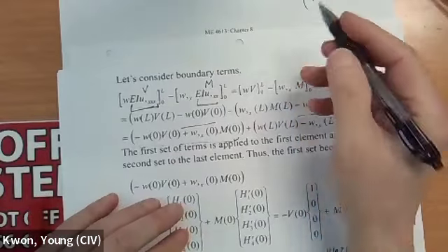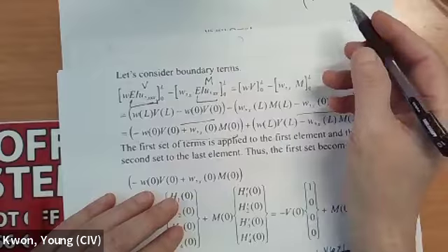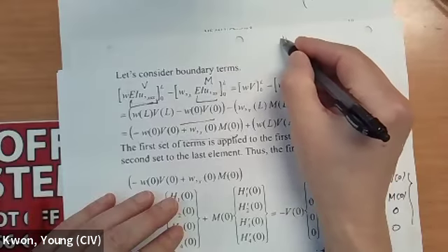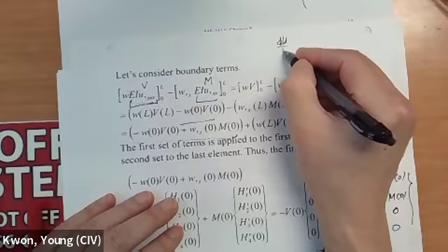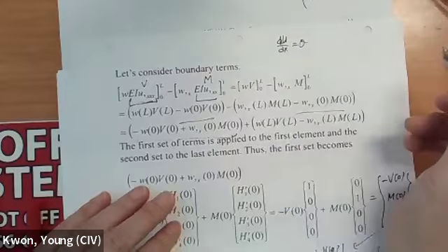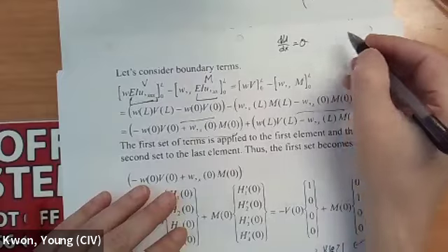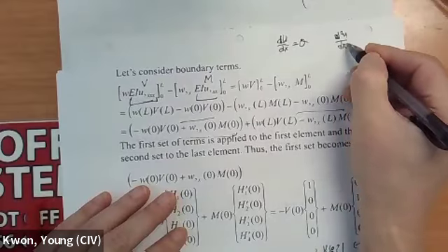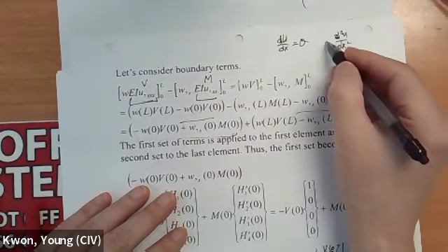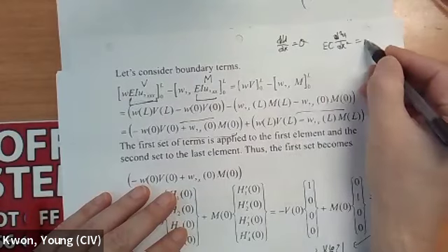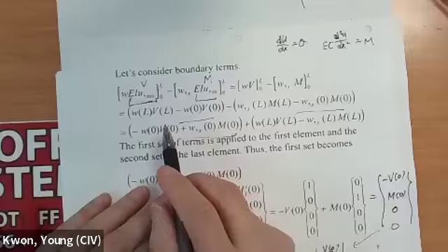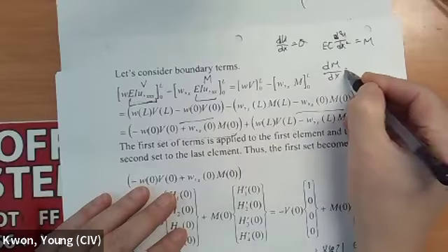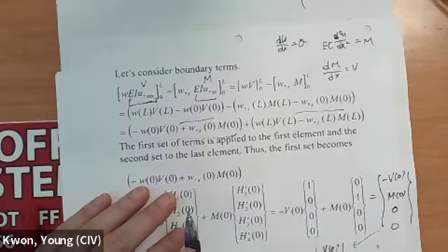In the derivation of that beam bending, you take a derivative of that, which is slope, right? And if you take a second derivative, and multiply by EI, that's going to be the moment. And then the third derivative is shear force. We know that.